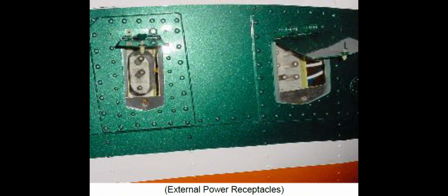DC external power relay. The DC external power relay is mounted on the upper right-hand beam in the nose electronics compartment at station 42. The DC power relay is a single pole contactor relay. It applies 28 volts DC power from the external DC power receptacle to the helicopter DC power system. Diodes. 4 blocking diodes function as gates during AC or DC external power application to prevent the flow of DC control voltage along undesired paths.